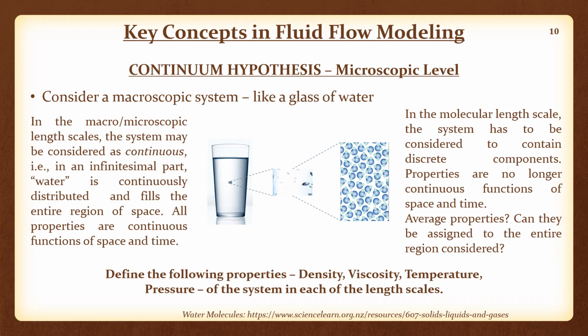There are only so many H2O molecules, and I am not arranging all these molecules in some sort of lattice structure in a liquid, like for example a simple cubic or a face-centered cubic, which is a close-packed crystal structure. And even such a crystal structure will occupy only 72% of the total volume. The remaining 28% will be void, and we don't consider any of that in a continuum approach, right?